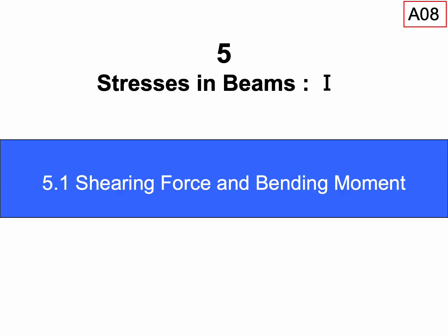A beam is fundamentally a structural element whose primary purpose is to carry loads applied transversely or perpendicular to its longitudinal axis. When we analyze these loads, we must first categorize the beam based on how it is supported.